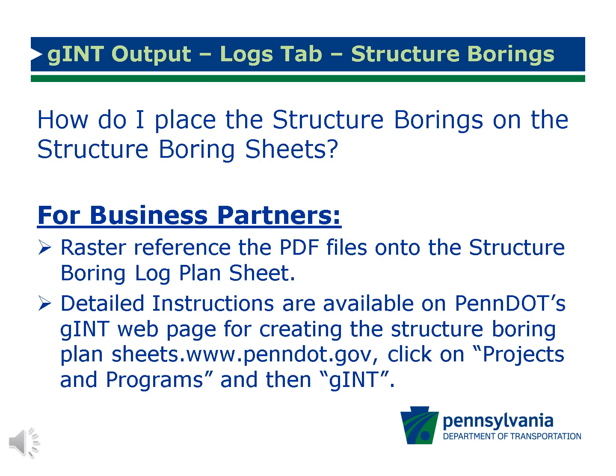The procedure for placing structure boring logs on structure boring plan sheets is different for business partners. Business partners should raster reference the PDF files onto the structure boring plan sheet. Detailed instructions for placing structure boring logs on the structure boring plan sheets using MicroStation are available on PennDOT's gINT webpage. Please note that lab testing information is to be displayed on the structure boring plan sheets. The information may be placed as space is available on the plan sheets, but it must be included.